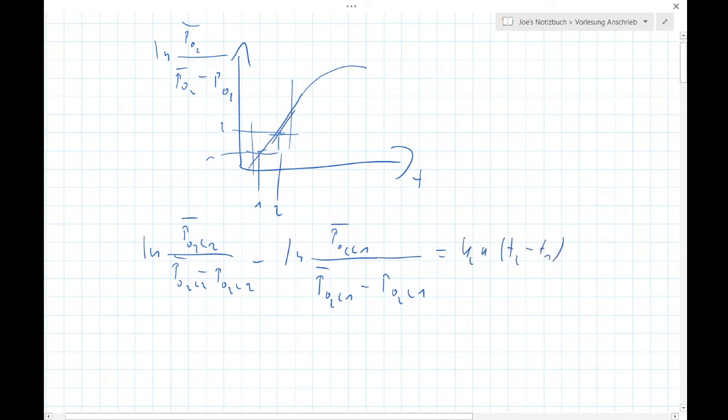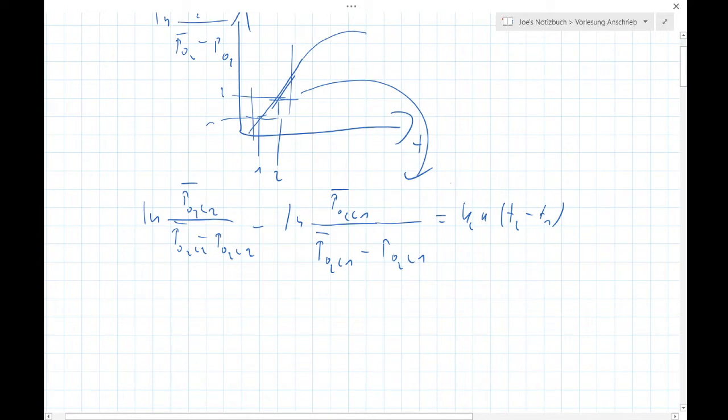That's just because of this equation. If you put that in one equation and divide, then this cancels out, and KLA is equal to, because the saturation concentration is always the same, this I could put like this, and then I simply put in my saturations.